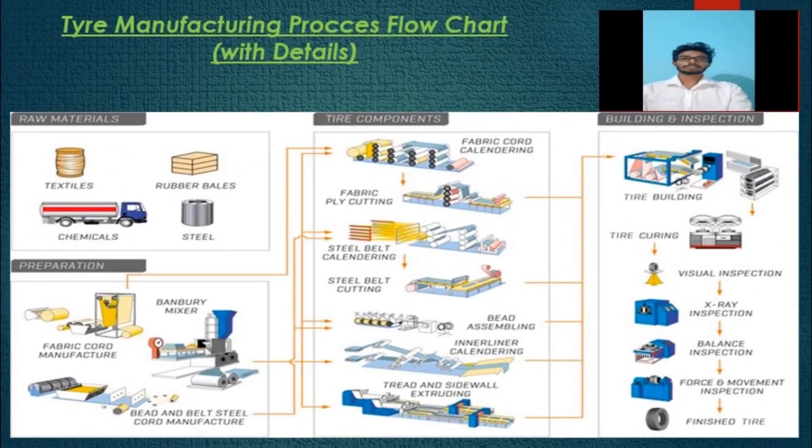When making tires, they first decide on the rubber mix. Then they mix it well in a big machine with spinning parts. This machine breaks down the rubber, fillers, and chemicals to make a mix. They are careful about how hot it gets during mixing. They do it in stages to keep the mix safe.